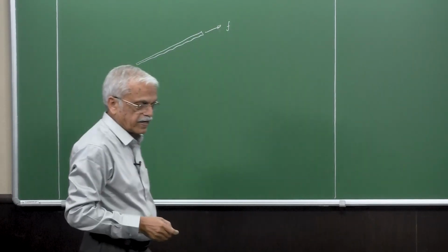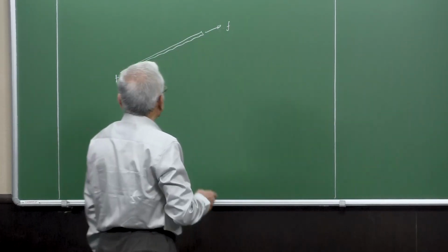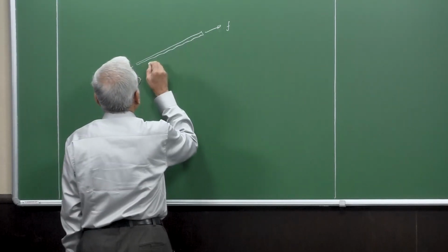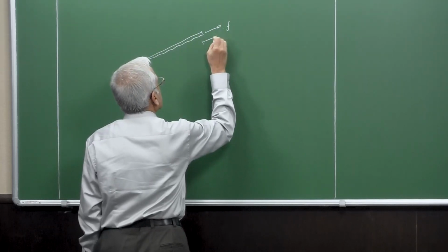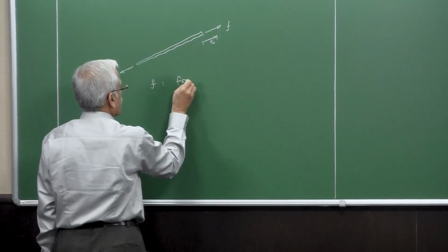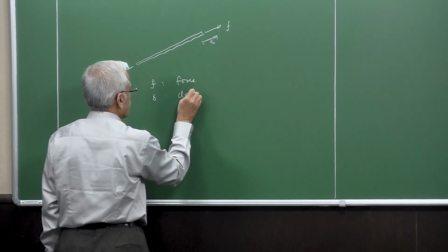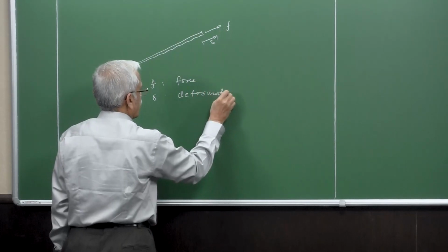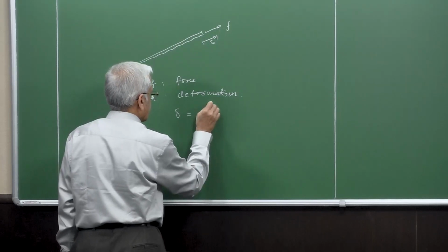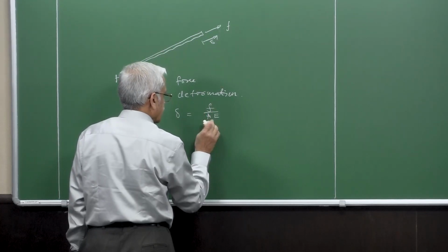and as we just said, the forces are only axial in nature, then the relationship between the axial force acting on the member and the deformation, say by an amount delta. If F is the axial force or internal force, and delta is the deformation, we know from simple analysis that the relationship is delta = F by AE, right?